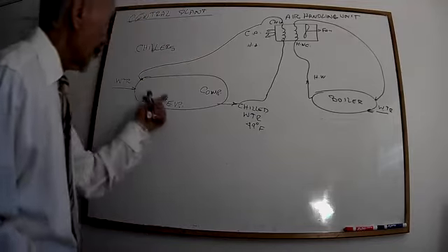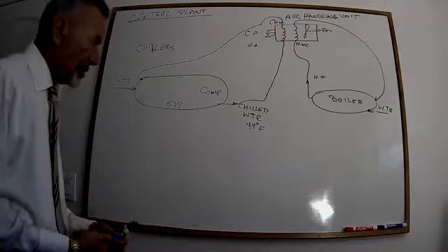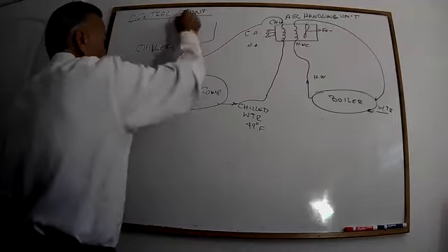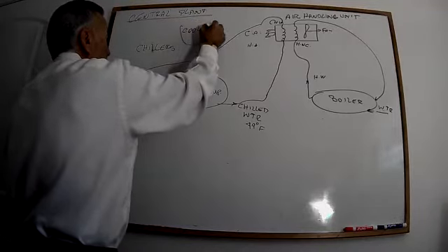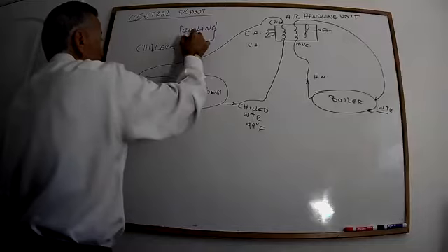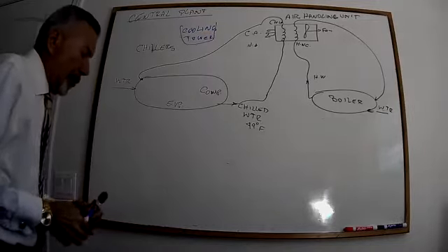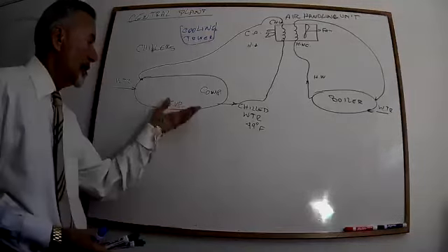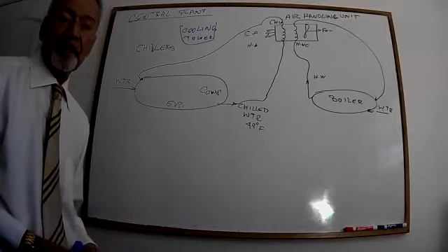And the condenser that we use for the chiller, that is what you see outside. It's a big, huge equipment, and it's called a cooling tower, which uses water to remove the heat from the refrigerant inside the chiller.